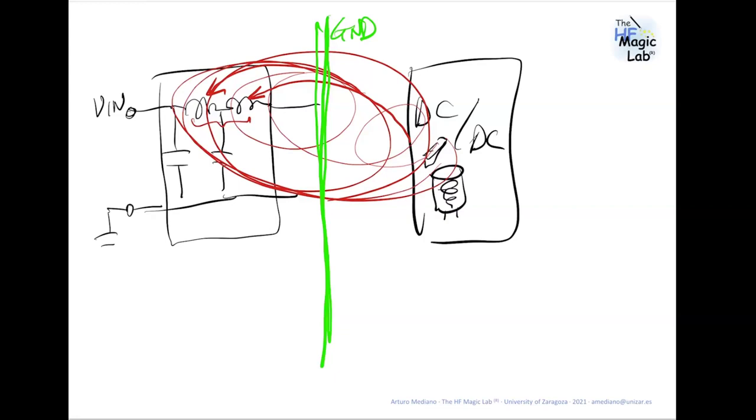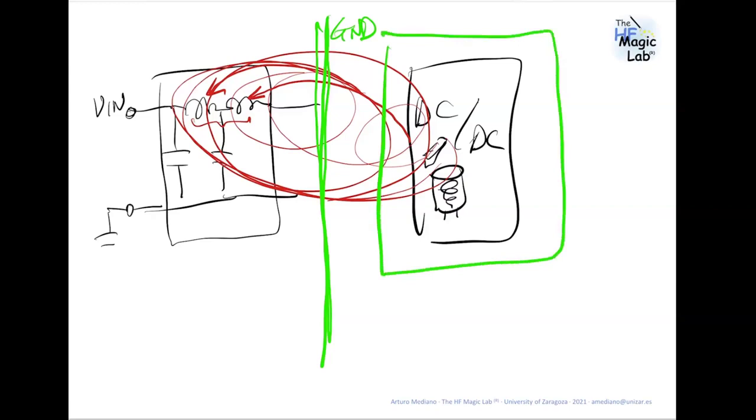In this way, you have less crosstalk, less coupling. So this is the same idea. Another possibility could be shielding. You could shield the DC-DC converter to minimize the possibility of injecting noise in the filter. Because if you inject noise in the inductors of the filter, this noise goes out, bypassing the filter.